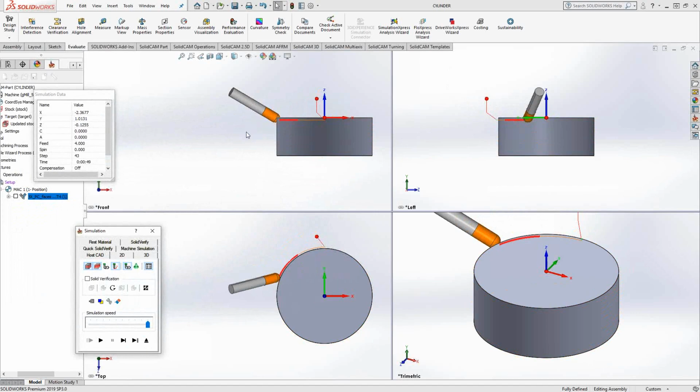So this toolpath option could be useful if you don't want to control it by the surface normal, or by one of the 3 axes, X, Y, or Z. You want to control it by just the contact point. This could be useful if the part you're doing 5-axis machining on changes direction very often, and it doesn't have a definable surface normal, maybe because it's a badly translated surface. This one is a much more sophisticated, much more complex selection of angles based off of nothing more than just the contact point.